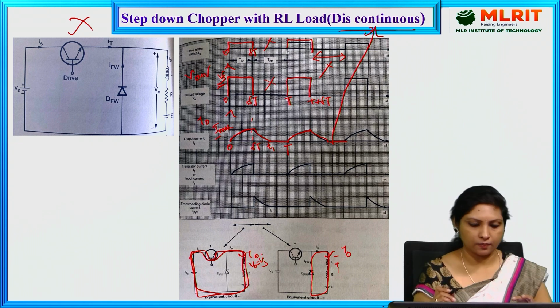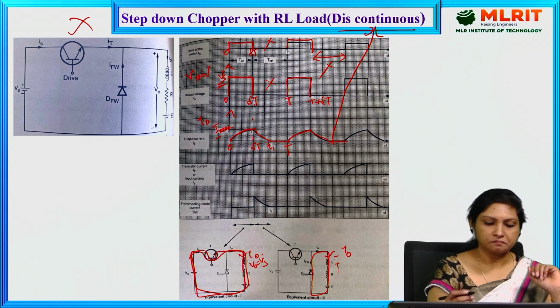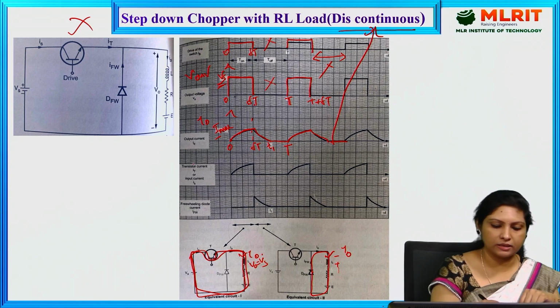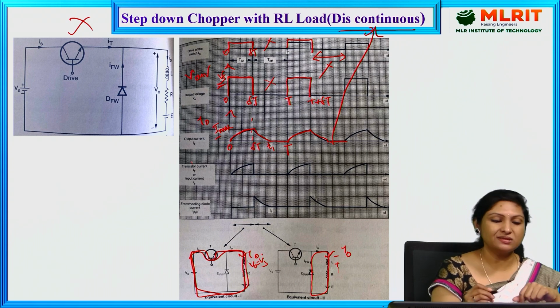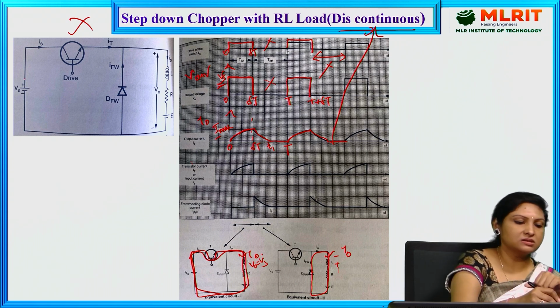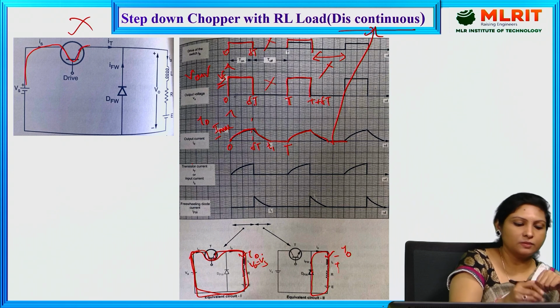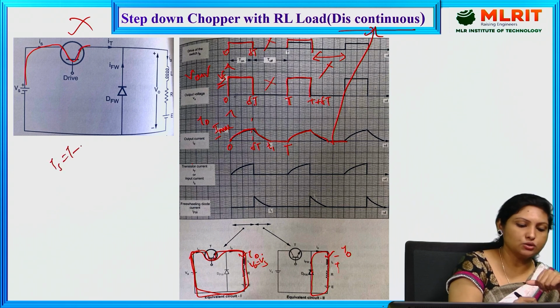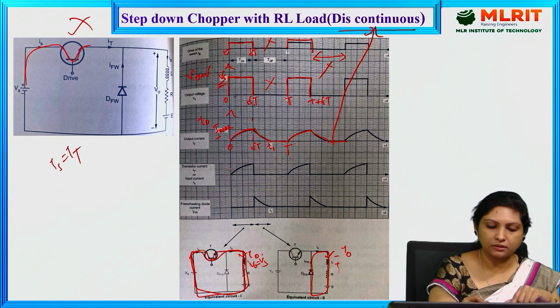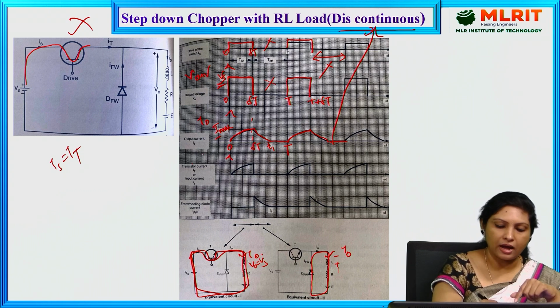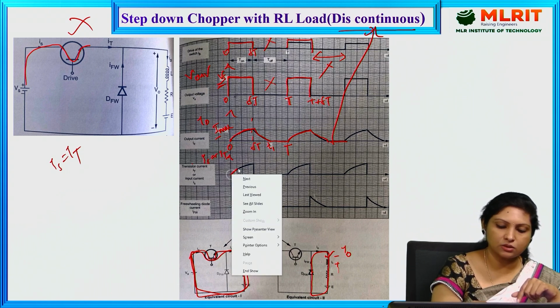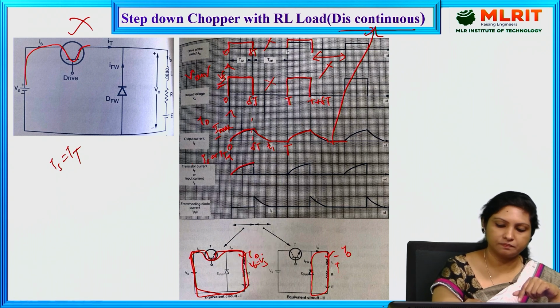And now coming to the transistor current. Here the transistor current or supply current is one and the same. See, here the supply current is what is flowing through the transistor. That means supply current is equal to transistor current. So here IS or IT will be indicated right from this instant called 0 to delta t.